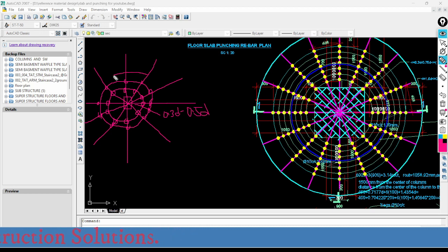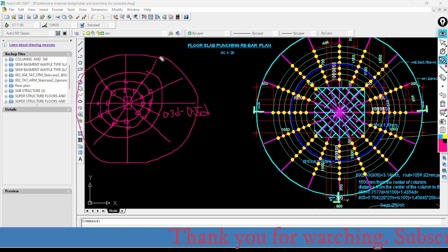And we need to place the third perimeter until we arrive at the outer perimeter. This one is the outer perimeter. So how can you calculate this outer perimeter? The outer perimeter, that is u out, can be obtained from what? From CSI SAFE. U out. If we get the value of u out, r out can be calculated.